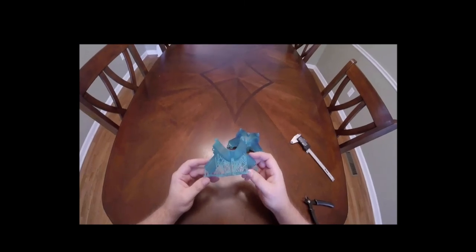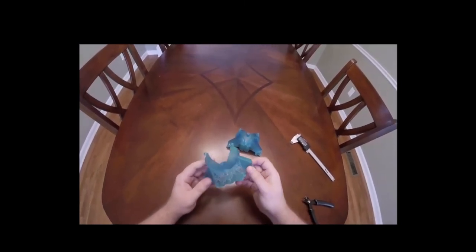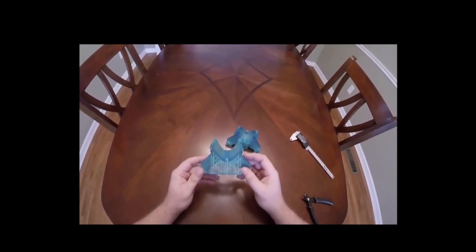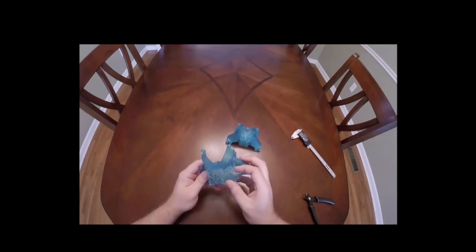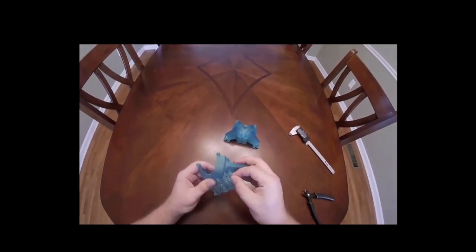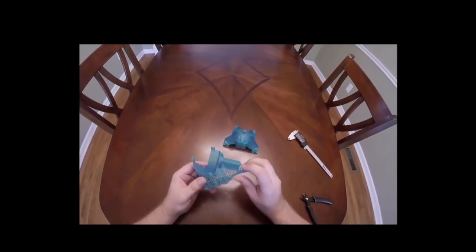And now all we have to do is remove these support structures, which people do a bunch of different ways. For me, it really depends on the type of model I'm doing. For something like a larger sort of engineering part like this, really I'll just be removing these supports in bulk, and you can see if you actually fatigue them a little bit, they kind of just break right off. The only thing to really note when you're just sort of breaking them off is that the support points will scratch the part.